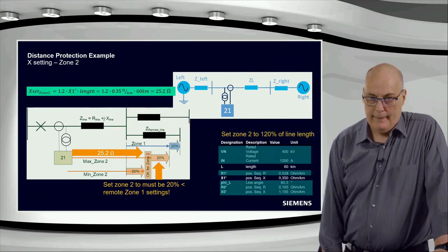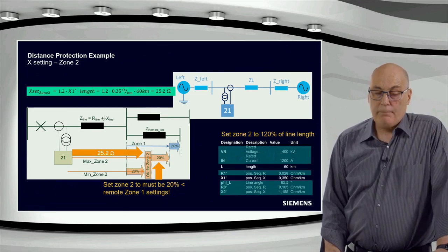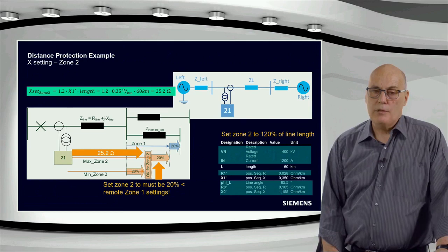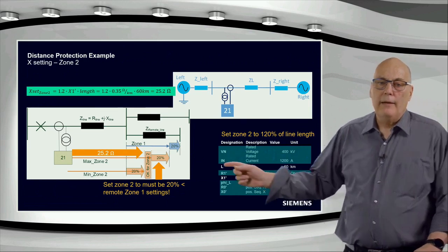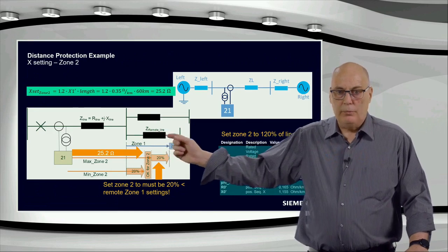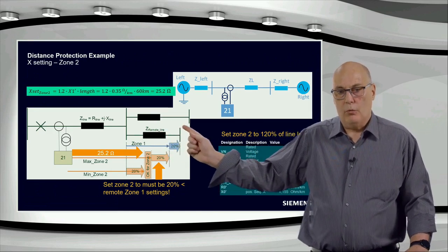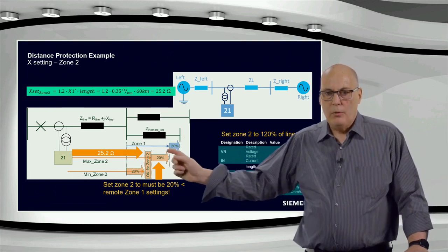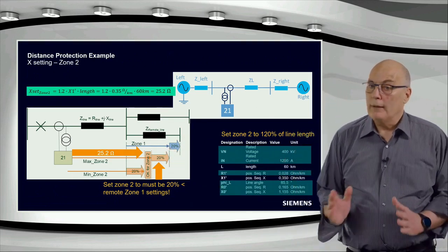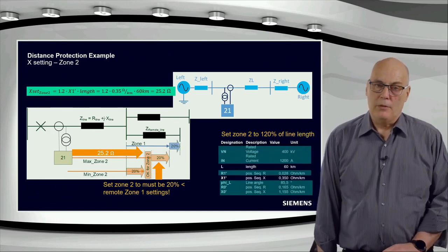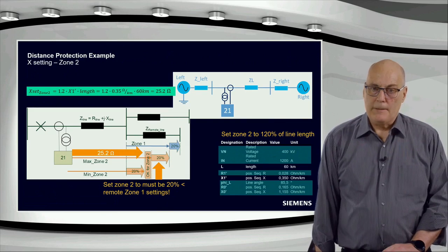on the right-hand side. That shortest feeder is going to, in our concept, have also distance protection, and that will have a zone 1 setting. So on that shortest feeder, and this would be this one over here, you can see it's shorter than the one on the top. That's our shortest feeder. It has a zone 1, this blue zone 1 over here. This blue zone 1 is a setting of the distance protection on this feeder here, the remote bus bar side, outgoing feeders.